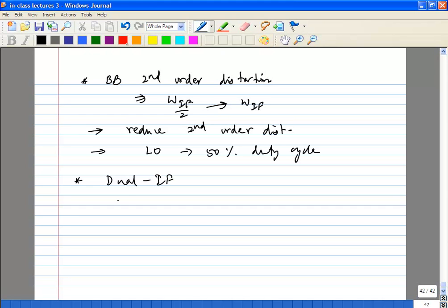The only thing you have to remember is, let's say it has IF1, IF2, you will have to do a second set of mixing to go from IF1 to IF2. You will have image reject problems there also. Because that mixer will have an LO and an IF1 input to go to IF2, and again you are going to have the corresponding opposite side of LO, omega LO plus omega LO2 plus omega IF2, you will probably have an image. Okay, so that is something you have to worry about. Okay, so that's as far as heterodyne systems.